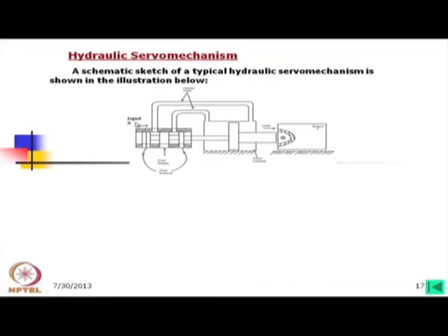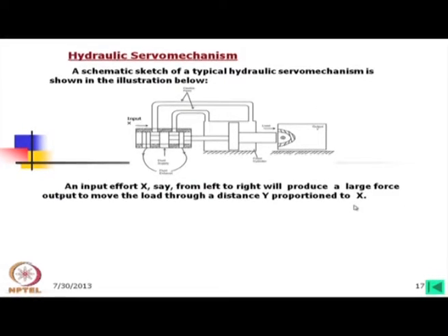When we give an input, then the load moves, but looking into position and motion, the valve body, outside body also moves, and by that closing the motion of the load, and again with the presence of input, the spool will move further and load will be moved. Now, if there is a feedback control within this system, then we shall call it servo mechanism, and there is a wide application of hydraulic servo mechanism starting from the machine tools to many other, say even in the missile control.